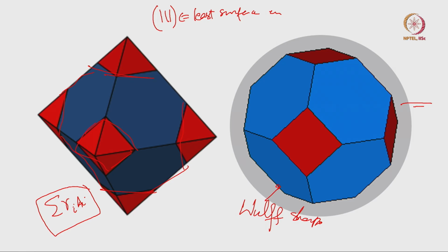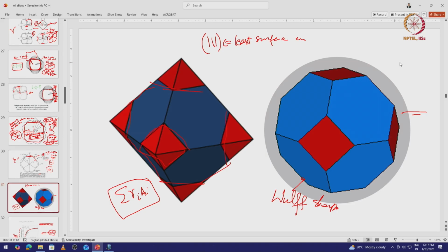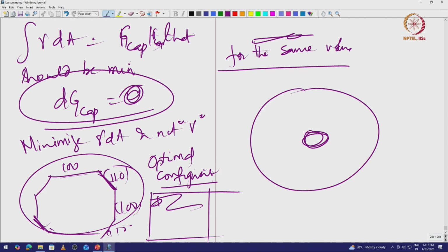Essentially, in any nucleation process, if the crystal is just nucleating, not on surfaces (on surfaces we'll go to interaction of interfacial energies and things like that in the next class), if there is any crystallization process, the crystal nucleating somewhere has to form surfaces, and if it is all thermodynamically nice, they will start taking what is called a Wulff shape. You can predict the shape of these crystals using Wulff construction.